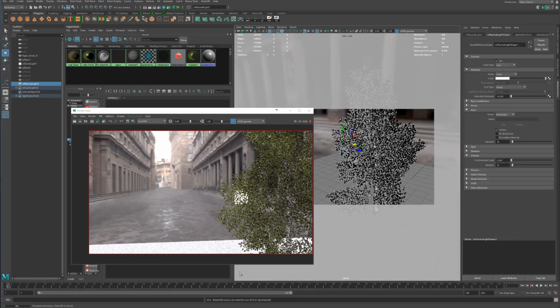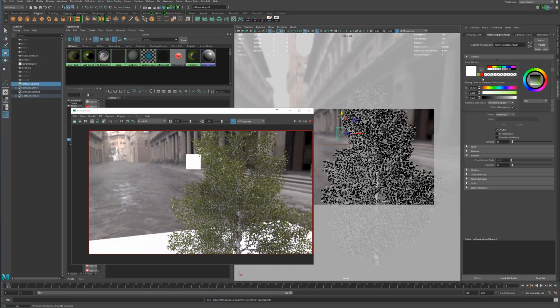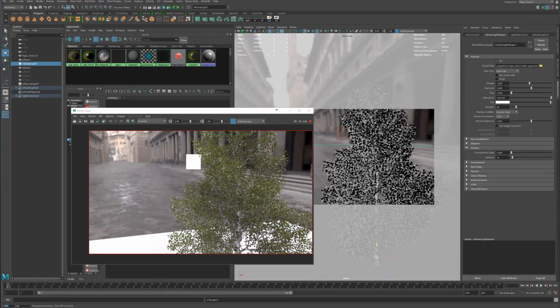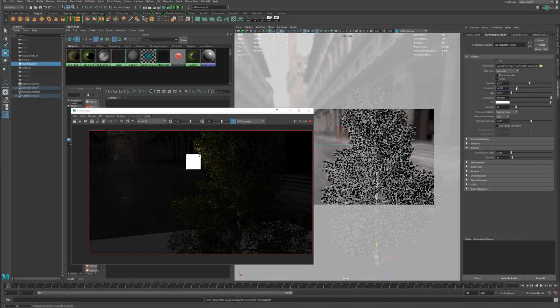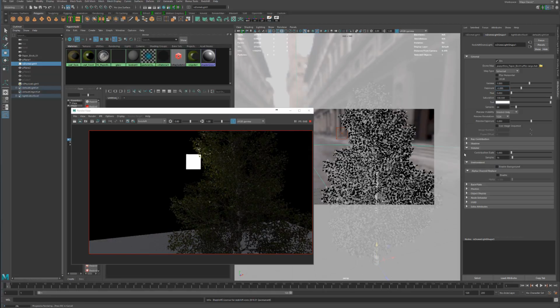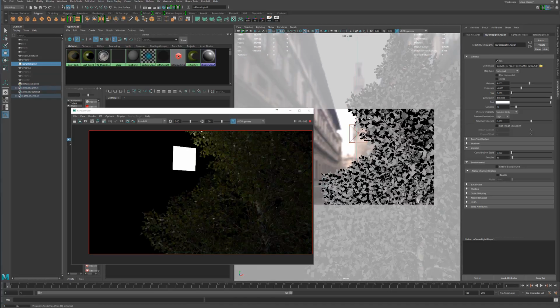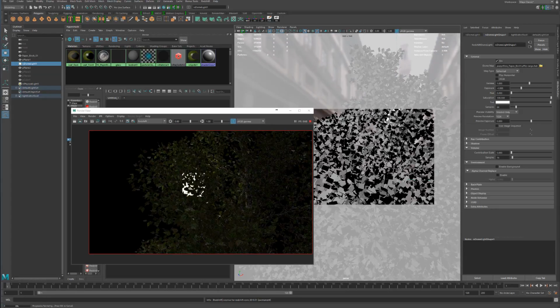And so we'll move this light back here. Let's make it a warmer color. Something like a little yellow. And let's tone down the dome light a bit so that it's not overpowering that smaller light. So I don't know. We'll just use it basically for a little bit of GI across the scene. And let's remove it from the visual. So right now the front specular is a little strong, but let's just get somewhere like this.